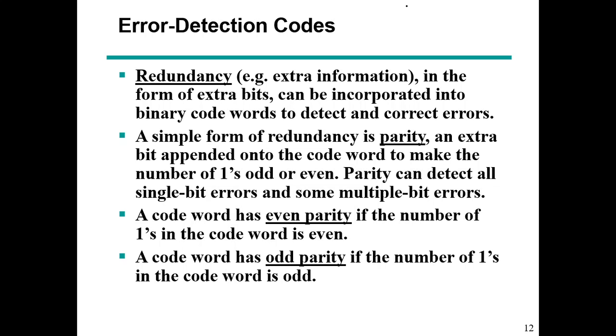So if you are using a 3-bit code to send different quantities, you have these combinations. 000, 001, 010, 011. Each is a valid code word. If any of them has an error, nobody would know whether invalid data was sent, because the receiver will always receive a valid code word.